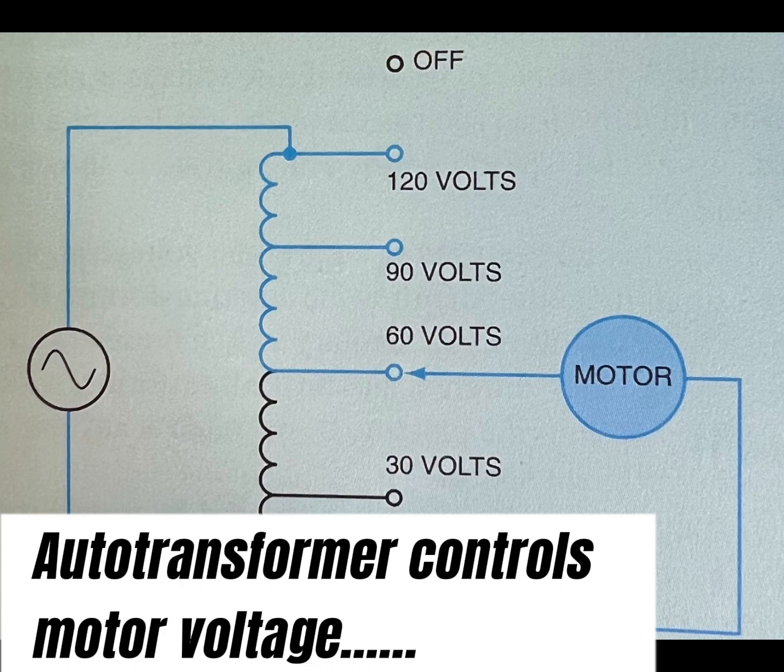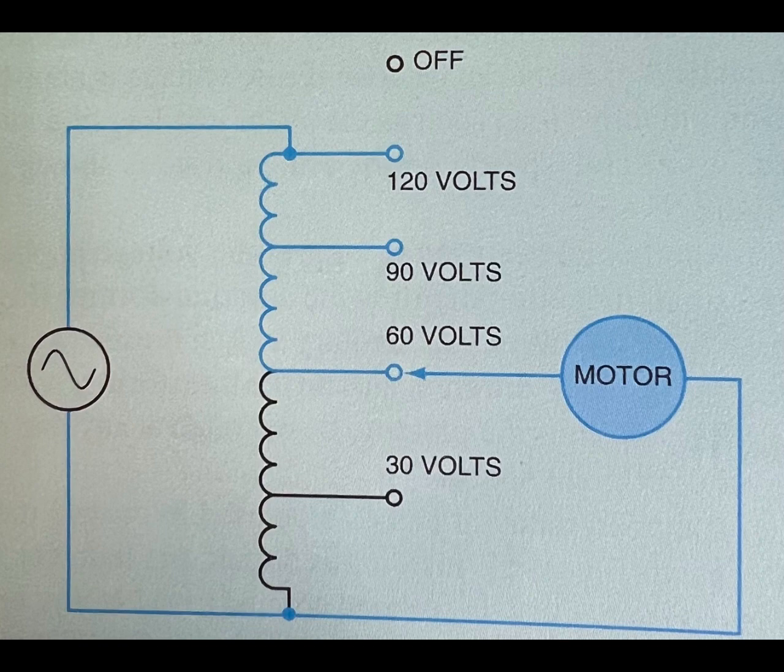Variable voltage speed control is used with fractional horsepower motors that operate light loads such as fans and blowers. Motors that are intended to be operated with variable voltage are designed with high resistance rotors, such as the Type A rotor, to help limit the amount of current induced into the rotor at low speed.